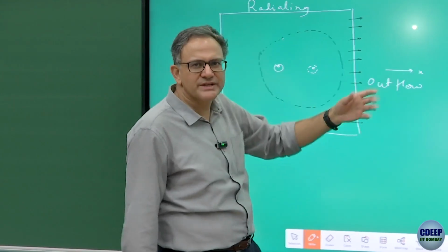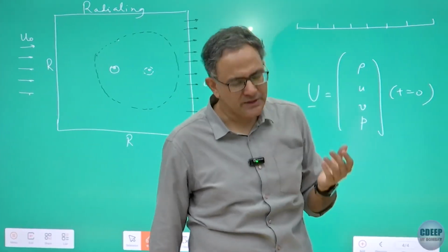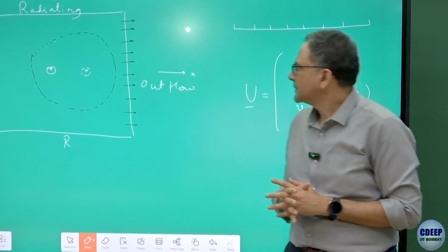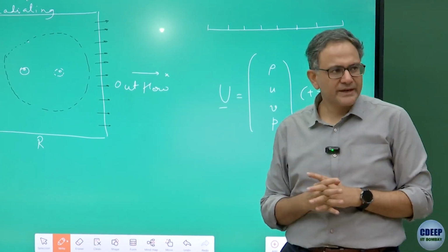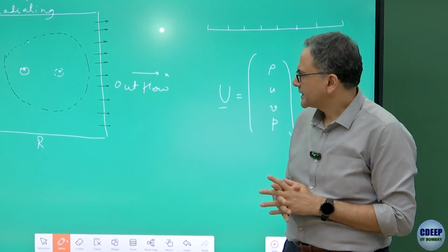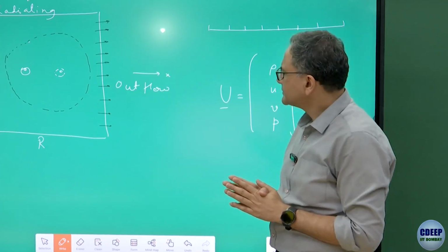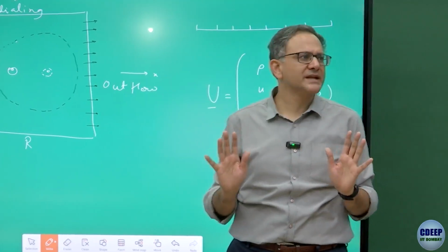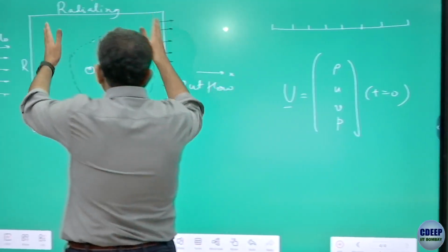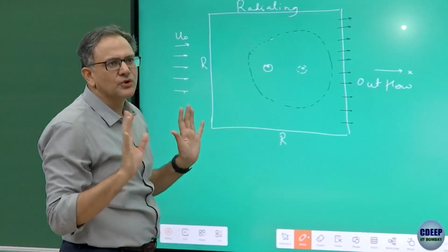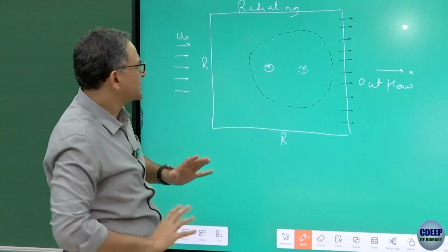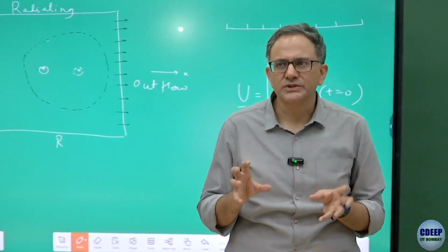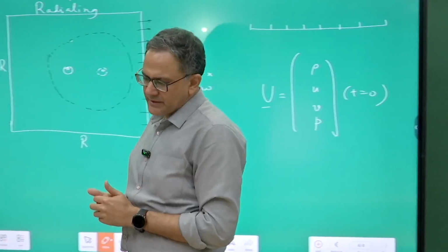The outflow boundary is a bit more challenging because it has to account for outflow, moving out of acoustic as well as the entropic and the rotational waves or vortical waves. Right now we are just again thinking of no other boundaries in our domain. The entire rest of the computational domain is all flow, and so there is no further boundaries to consider right now. But again, the textbook does solve for solid walls also, and you can implement that if you've got the time and play around with that.